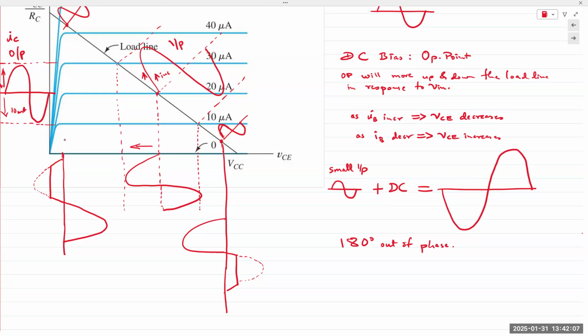One drawback of this kind of circuit is that it is highly dependent on the beta of the transistor. Okay. So if a transistor is rated for 100 current gain, and you take it out, you plug a different transistor in there, perhaps the exact same model, perhaps even manufactured at the same time on the same substrate, but the beta could be highly different. Instead of 100, it would be 150, it would be 200. Okay, and it does happen in real life. So if that happens, then the circuit is not going to function as it's supposed to.